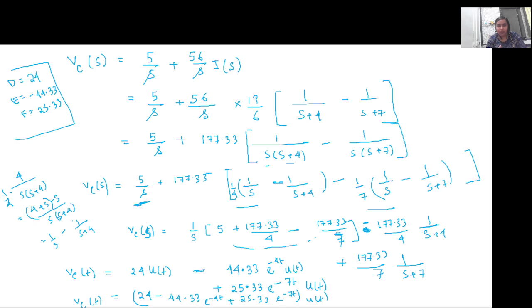So basically in all of these problems, first step, figure out how the circuit is. If there is any mutual inductance involved, sort it out and write it in terms of proper equations. Then redraw the circuit in the S domain and work out the solution. Then when you get the final expression, you make sure that you have